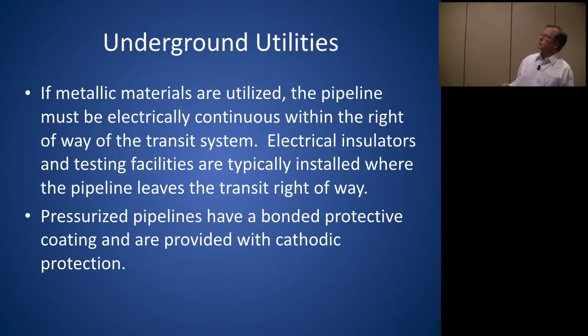We kind of said that. We're going to make it electrically continuous. We'll add cathodic protection to it. Pressurized pipelines, we always do that. Gravity pipelines, it kind of depends.